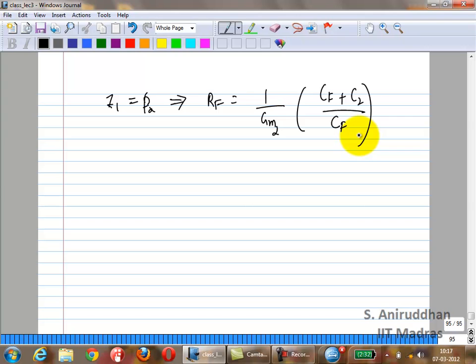Okay? However, if you look at the transient response, you will get an exponential component. Let's say you put a step response through this. Normally for a single pole you expect a first order exponential, but if you add a pole 0 doublet, what you will see is there is a second exponential, the time constant of which depends on the spacing between these two. Okay? In other words, as the spacing gets smaller and smaller, the time constant will get larger and larger. It will take longer and longer to settle. Okay, so that is why this is such a big problem. In the previous case, not a big problem. Here, it is a very big problem.